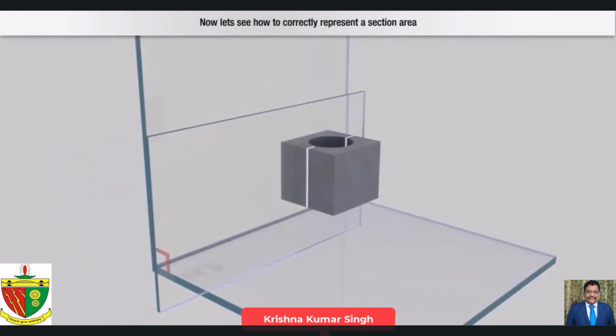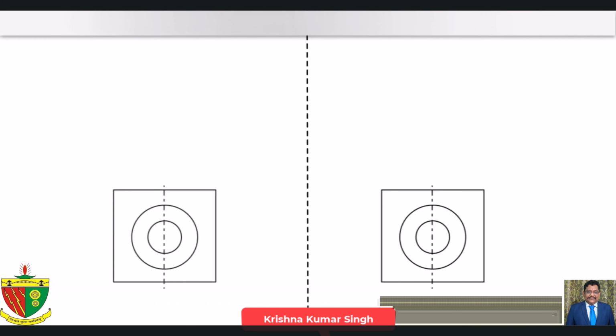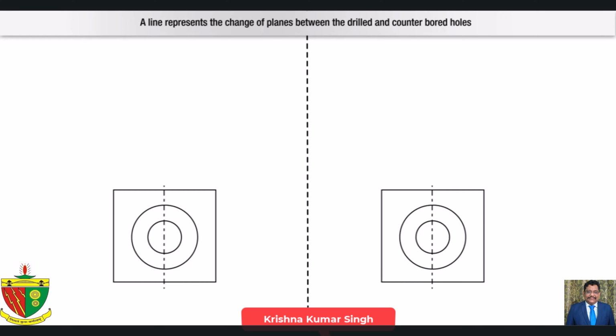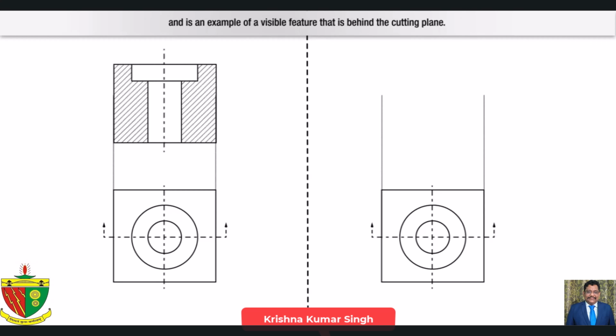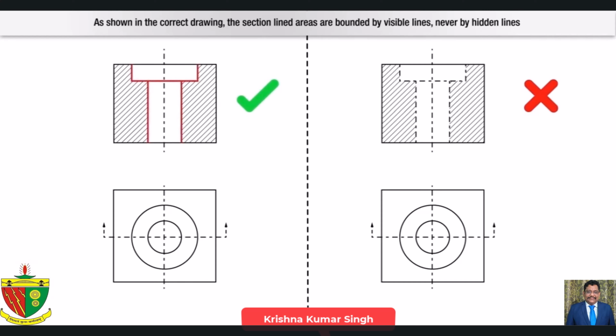Now, let's see how to correctly represent a section area. The figure shows a section view for which the cutting plane passes through the center of a counterbored hole. A line represents the change of planes between the drilled and counterbored holes and is an example of a visible feature that is behind the cutting plane. As shown in the correct drawing, the section line areas are bounded by visible lines, never by hidden lines.